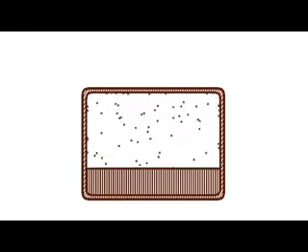Now, the reverse of that holds also. We require heat to change to a gas, but we produce heat when changing a gas to a liquid, and we'll call this condensation. So coolant that is evaporating or boiling is cold, and coolant that is condensing is warm. That's important.